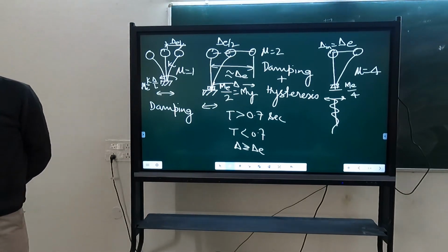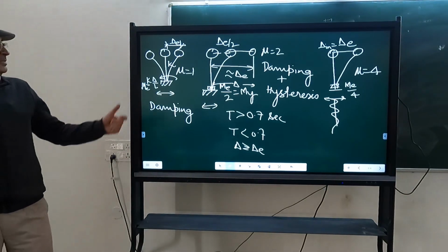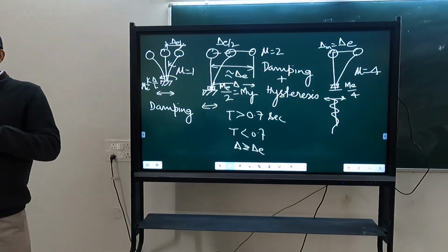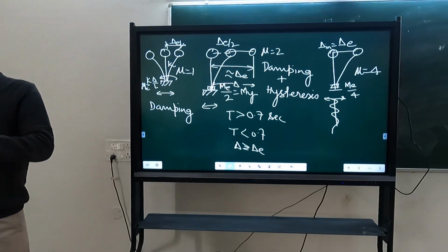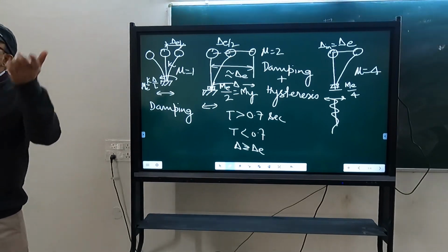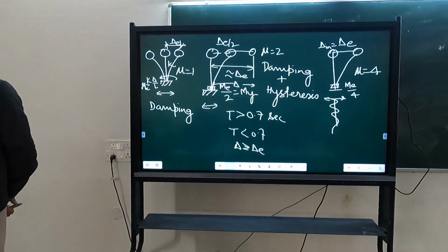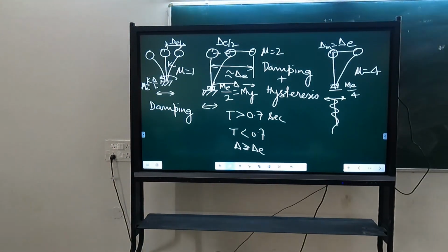Final question is that in this case, ME is the moment demand on elastic structure. If my structure has to remain elastic, it doesn't yield, then how much moment will develop? That is ME. ME is not provided. ME is what earthquake will require if my structure has to remain elastic. How can I know that? How? By simple analysis. Take the structure, subject it to earthquake, perform analysis, linear analysis, which you have learned in the last semester. Perform that analysis. You will get the moment which is required.